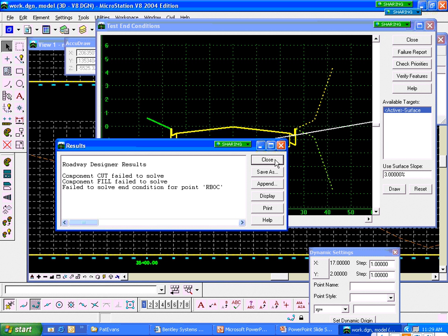Now, this is one of the things I spoke to earlier. In the past, you would put together a decision table or a cut fill table and run it, and you have portions in your model where nothing happened. You couldn't for the life of you figure out what was going on. With the test feature we have now in 8.7, we can test these things and see exactly what the condition is that's making it fail.